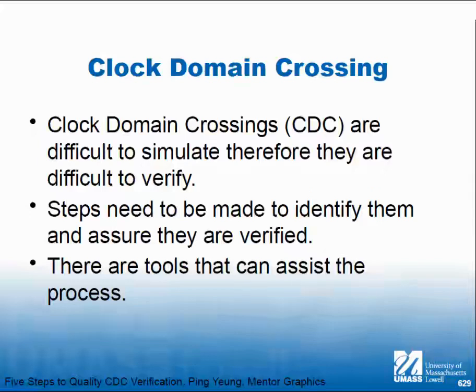So the guideline for developing implementable digital circuits is to have one clock. And in general, everything that you design has one clock, except you might have more than one thing that has to talk to another thing, and they have different clocks. So there are techniques for connecting them together.